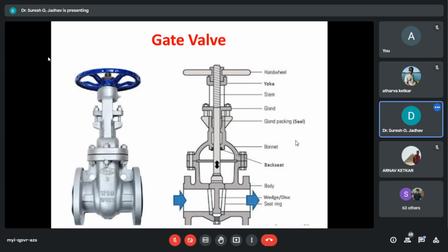Lantern is provided for higher ratings if required. When lantern is provided, the stuffing box shall be provided with 2 plug holes. The material of lantern shall have corrosion resistance equal to that of the body. Normally, the packing is of braided asbestos with suitable corrosion inhibitors.